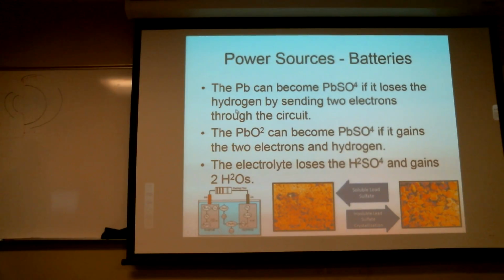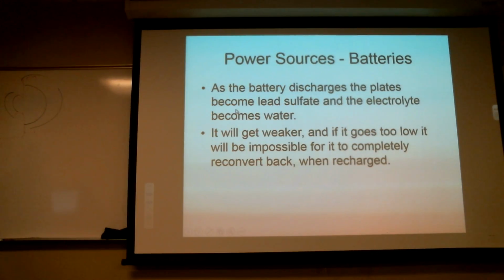And we're adding distilled water for what reason? Well, we don't care that it's distilled, we care that it does not have contaminants. Deionized, we don't care, we just don't want the contaminants, we want pure water. Contaminants are usually base minerals, so they neutralize the acid anyway. Got it. Does that change the density as well? Well, it just neutralizes the acid, they react and do nothing. Okay.